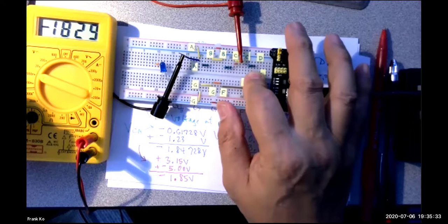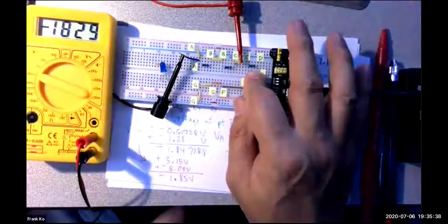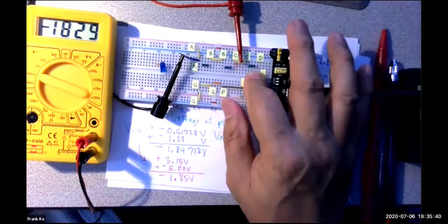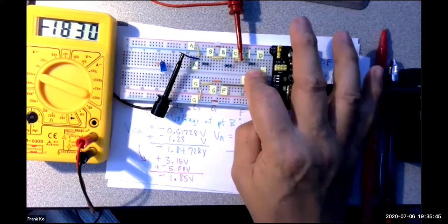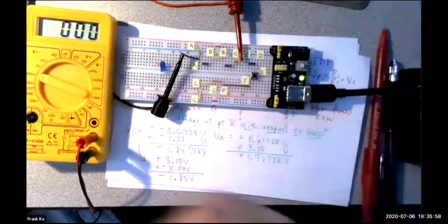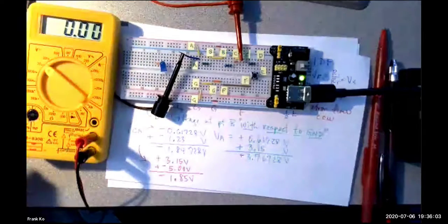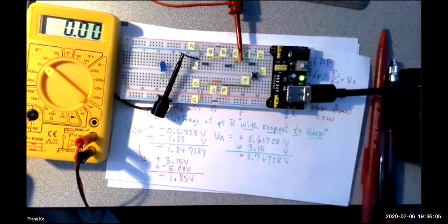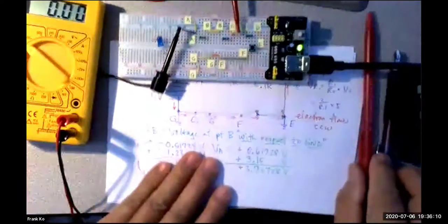Any questions about measuring voltages between 2 points, especially with this exercise, especially with 2 different ways of determining that value of voltage? Is this helpful to you? Yeah. Do you think I could do the same thing with an open switch too? Yeah, I have an open switch right now. And what do we have? We have 0 volts. And I'm going to go up to 20 just to make sure we're on the appropriate scale. And why is this going to be the voltage at 0?